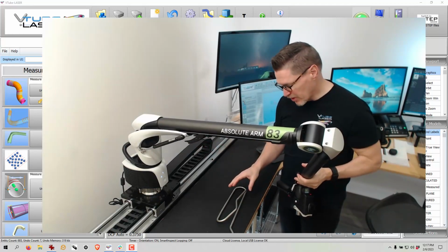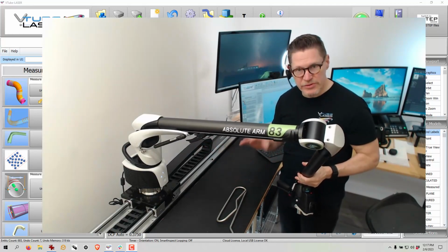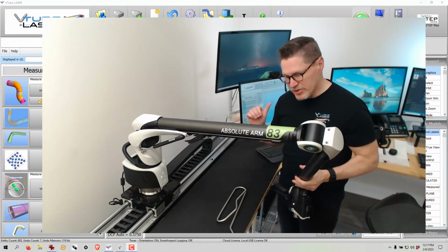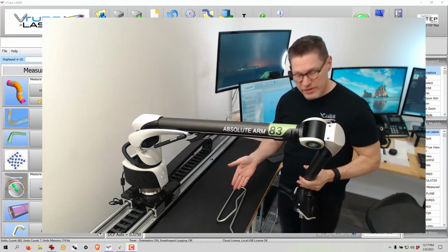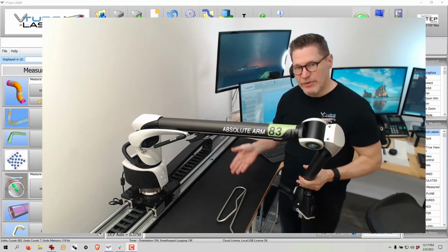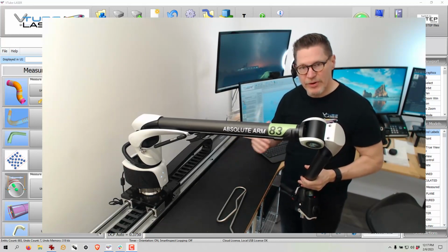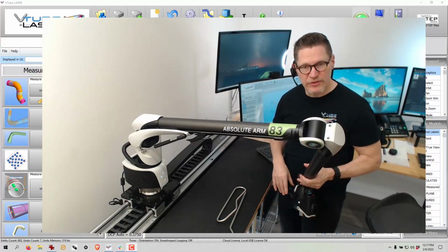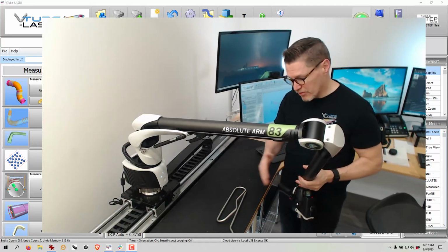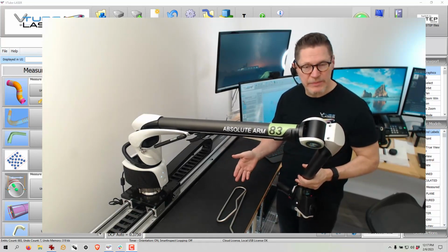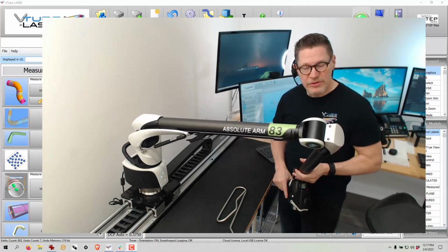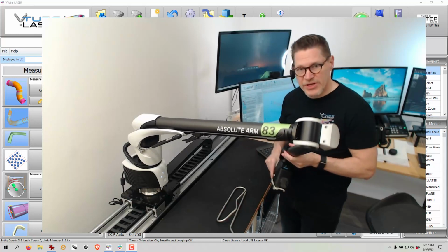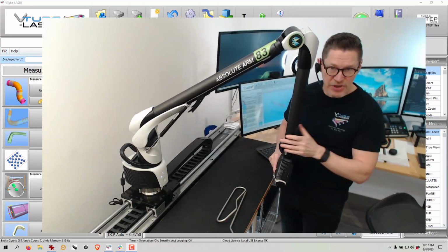And in this case, what I'm going to do to prove this concept to you and to show you how to test for it is I'm going to set the diameter cut plane to 0.375 inches or 3/8 of an inch, the diameter of this part. And then I'm going to turn that on and off during point cloud scanning. And you're going to see the result. It also shows you how to practice with the diameter cut plane so that when you go to measure the tube, you know how to use it in order to measure the tube effectively for scanning positioning. So let's get started.